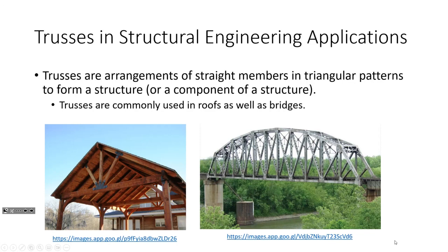The advantage of a truss from a structural standpoint, so I do want you to understand when you would use a truss and when you wouldn't. Trusses are, from a structural standpoint, very lightweight and very efficient. What I mean by efficient is that you get a lot of structural stiffness for very little weight. Stiffness is the relationship between applied forces and resulting deformations. And pound for pound, trusses are among the most stiff structural systems we can employ. So they do have advantages in that regard.